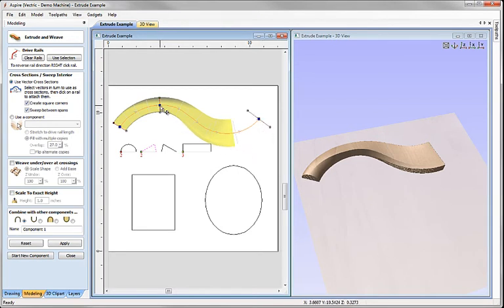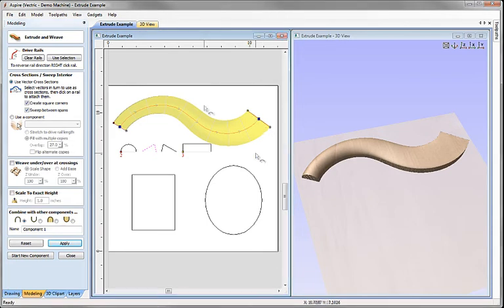I could even come in and right mouse click over a cross section, choose the option to delete cross section. If I hit apply, we'll have gone back now to a shape that goes all the way from the start and end between our half round and our rectangle. There are other options under the right mouse click menu depending whether you click over a cross section. If we right mouse click there, you can see we can adjust the smoothness of the shape, delete as we just did there, or add to all rail nodes that we'll look at in a moment.